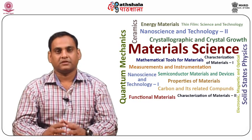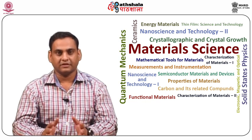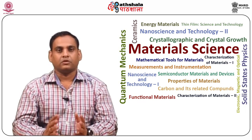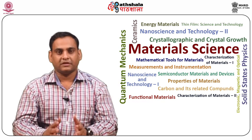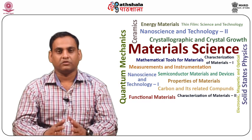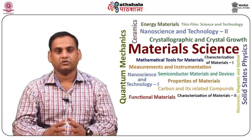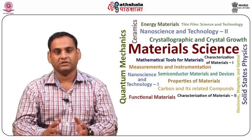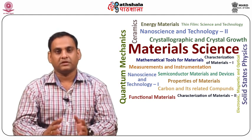Soft magnetic materials. Most of the magnetic materials of industrial interest are ferromagnetic materials. The ferromagnetic materials can be categorized into two: one is soft magnetic materials and another is hard magnetic materials. A ferromagnetic material in the demagnetized state does not show magnetization, although it has spontaneous magnetization. This is because the ferromagnetic materials are divided into many magnetic domains. Within the magnetic domain, the direction of magnetic moment is aligned.